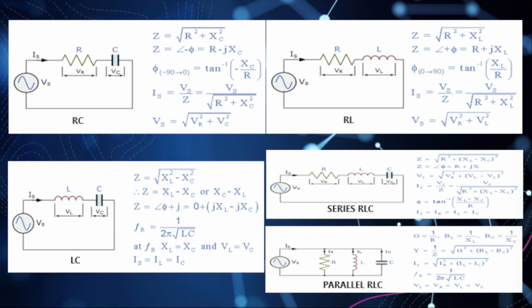You have RL circuits. They're common in RF amplifiers and DC power supplies, where the inductor in our RL circuit is used to allow DC bias current, but acts primarily as a choke, or blocks, if that makes for a better understanding.